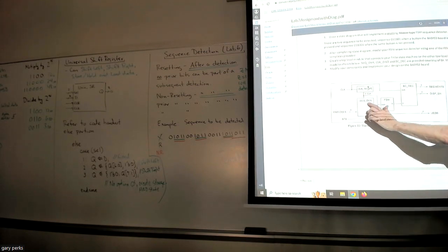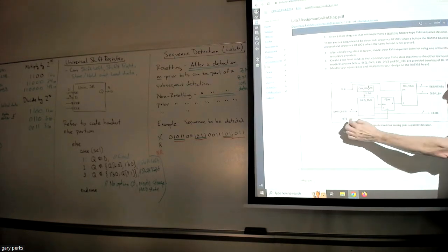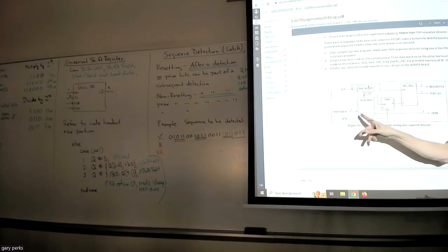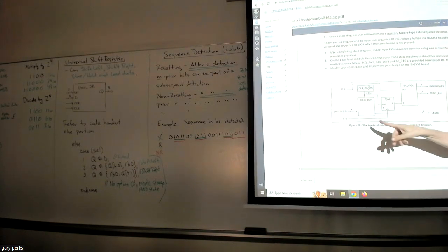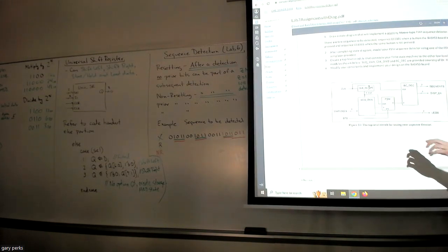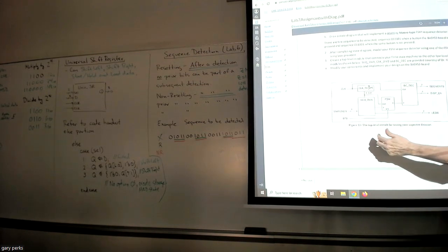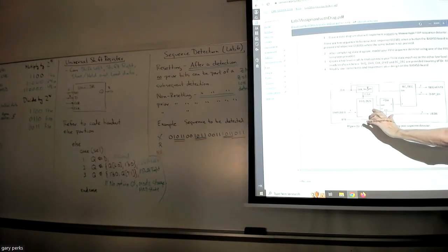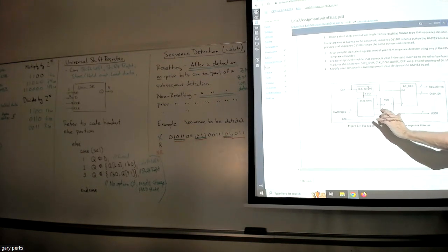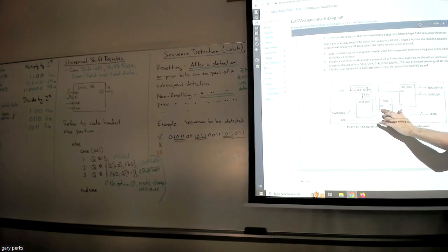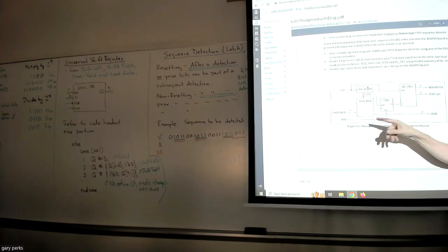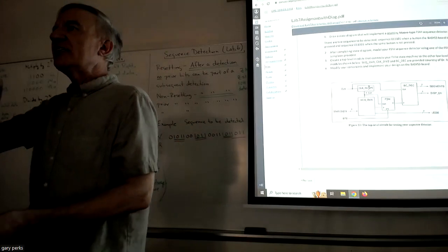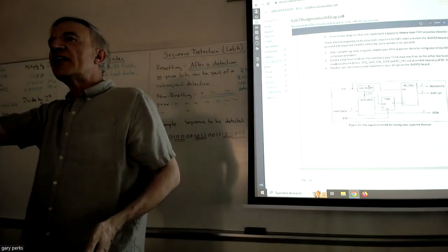And if you take a look at the sequence driver, the inputs are switches, 8 switches. So you're going to have 8 switches on your board, and the data that you set the switches to is going to be inputted to the sequence driver. I keep saying divider when it's driver. And then the sequence driver just has a single bit output that you're going to connect to the X input of your FSM. So what this sequence driver is doing, it's taking the 1s and 0s that you set the switches to, and it's putting those 1s and 0s all on one output.